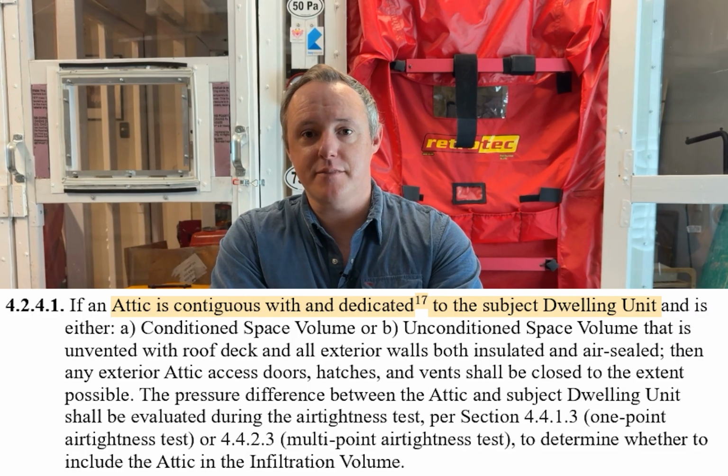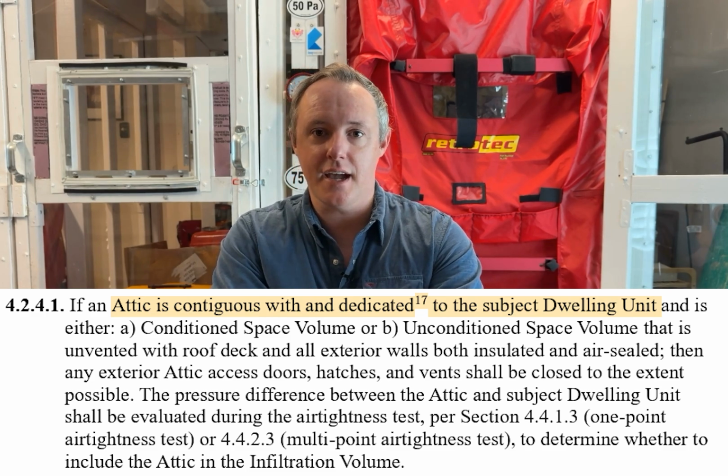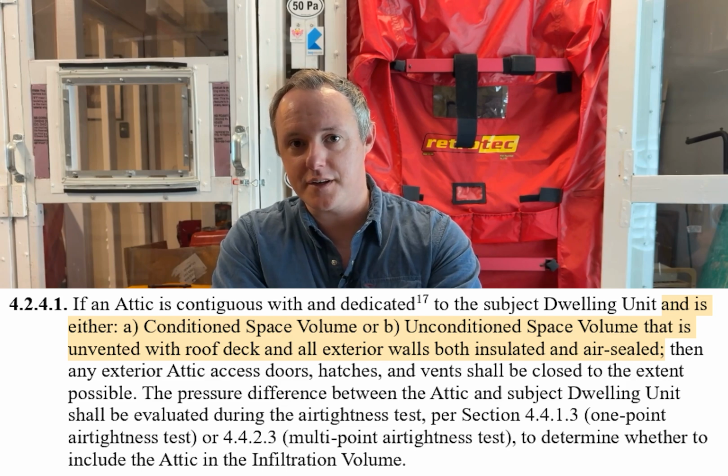So the first one is that the attic must be specifically dedicated to the unit that you are testing. So for example, if you were testing a duplex and the two units share an attic space, then you cannot include that attic as part of your infiltration volume. Now, if we're talking about single family homes, that should always be true.